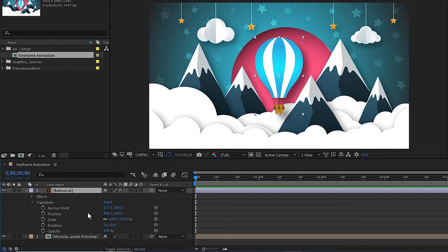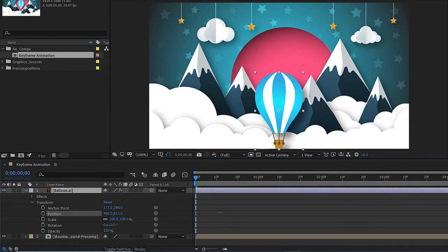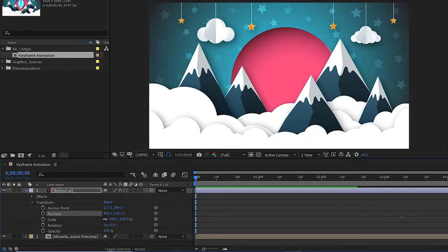If we look to the right of each of these parameters, we see blue numbers. The left number here is for the x-axis, which is the horizontal axis. And the right number here is for the y-axis, which will move the balloon up and down. So let's start by clicking and dragging by holding our mouse down, and we'll drag to the right directly over the y parameter and scrub until you see the balloon disappear off the bottom of the scene.